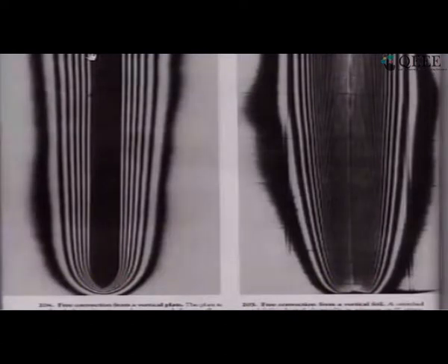And in fact, you can go back and measure the distances physically, and from the image you can get the distances between the fringes, and you can correlate that fringe spacing to density gradients, which in turn can be correlated to temperature differences. So you get a complete map of the temperature field that I was just qualitatively drawing there from an experiment like this, where we did not use anything else but interferometry, and it gave us a huge amount of information about the temperature field.